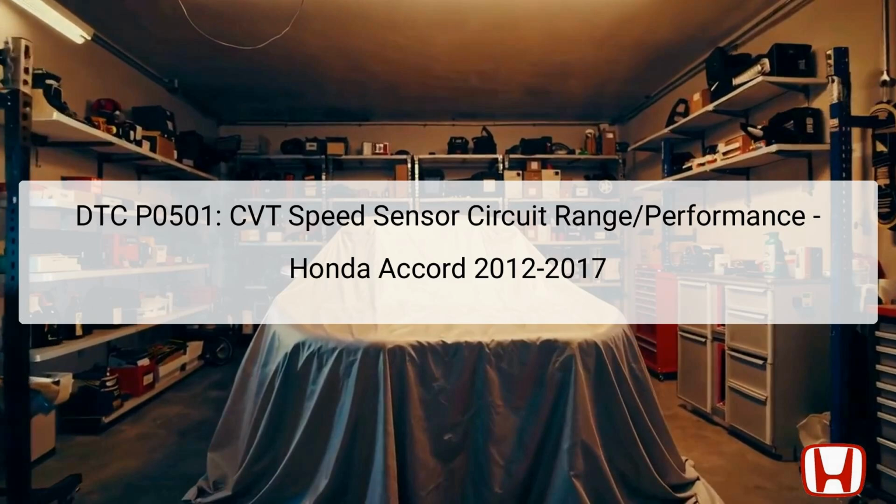The Honda Accord from 2012 to 2017 is equipped with a continuously variable transmission, CVT, which relies on a precise communication between various sensors to ensure optimal performance. The Diagnostic Trouble Code, DTC P0501, indicates an issue with the CVT Speed Sensor Circuit's range or performance.